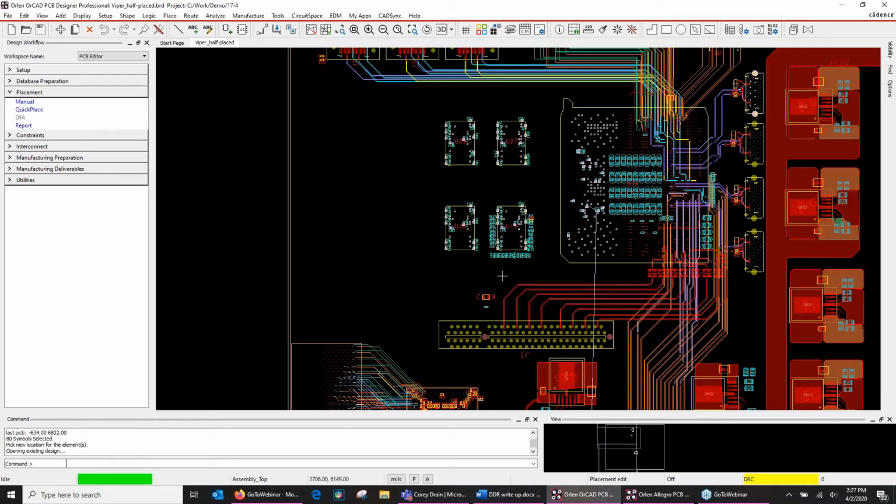What we're going to have is, I went ahead and, to save time, did the placement with some first memory bank. I've got that placed, and I got the termination in there at the end. This is going to be routed in kind of a C horseshoe fashion on there, but I need to get the rest of the chips on here. Now, following our flow, I need to do a placement to get the rest of the parts on there.